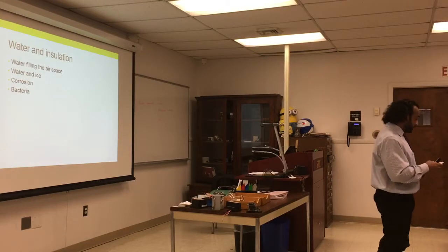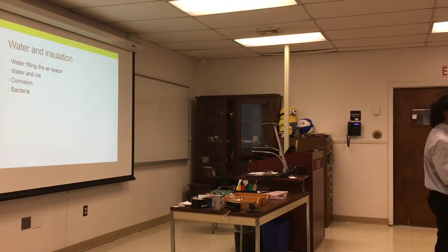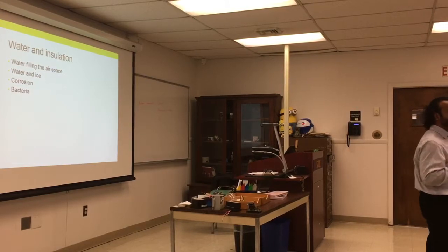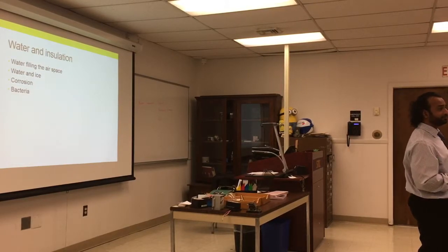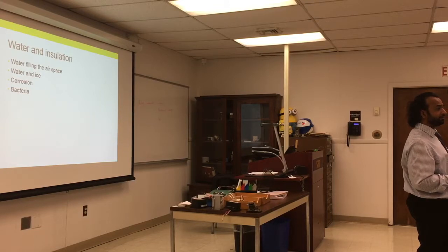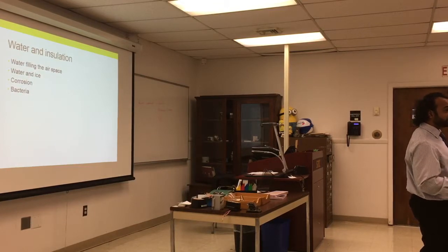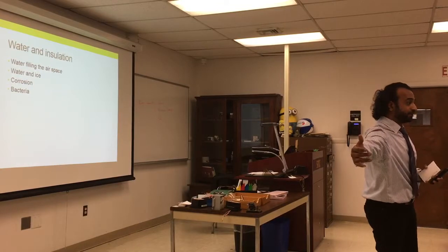Another question: how about tracing? When you have a gutter that collects water from the roof, where does it terminate? It goes down the spout to the ground. Usually they don't want it to go near the house. You want to be at least 3 feet away from the house.